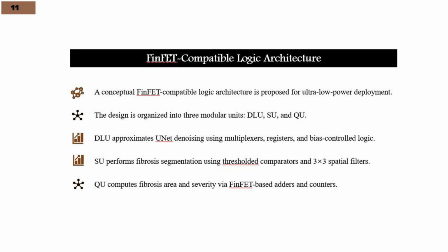Okay, this slide presents the FinFET compatible logic design. This slide details the internal logic design of the FinFET based modules. Now, as we showed in the previous slide, there are three modules: denoising, segmentation, and quantification. Denoising is approximated using multiplexers, resistors, and bias control logic, while segmentation relies on spatial filtering and comparator circuits, and quantification uses adders and counters to compute fibrosis area percentage.